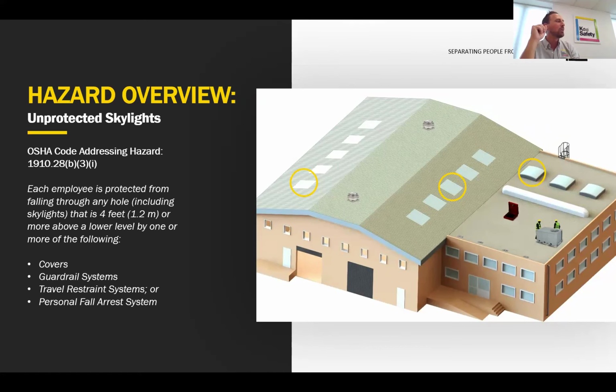And number two, what happens to skylights when they get something over top of them, right? What happens to skylights when there's a little bit of snow on the roof, maybe a little bit of dust on the roof? You get that sun blindness, white roof with a white dome, and it's really bright outside. They're hard to see. The skylights are hard to see, and you can step on one without realizing it, and you can fall right through.